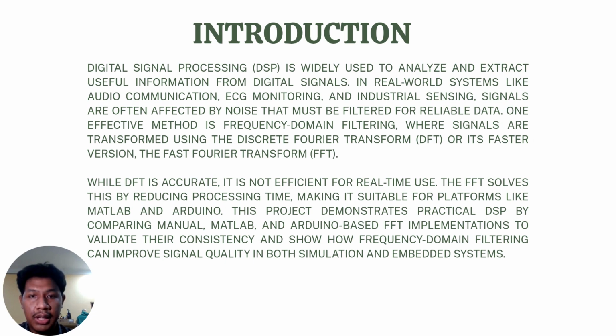using in this project. This project demonstrates practical DSP, comparing manual data, MATLAB and Arduino-based FFT implementation to validate their consistency and show how frequency domain filtering can improve signal quality in both simulation and embedded systems.